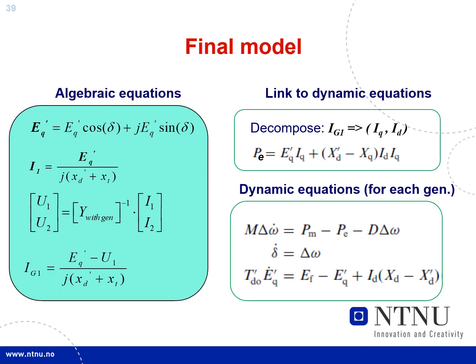So then the final model will be to link the dynamic equations with the algebraic equations. And then one has to keep in mind here that the internal transient voltage is usually modeled in the reference frame of each generator. So it has to be transformed to the correct angle, which is in this case the angle between these machines.